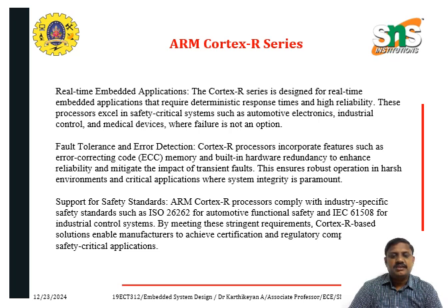The Cortex R series is designed for real-time embedded applications. It requires deterministic behavior and high reliability, such as in medical devices where failure in operation is critical. The main application is in automobile electronics. Fault tolerance and error detection are mainly used for the Cortex R series, along with error correcting code, ECC, to build hardware redundancy and enhance reliability. It also supports safety standards such as ISO 26262, which is very useful for safety, and IEC 61508 for industrial control applications. These are the main applications of the Cortex R series.